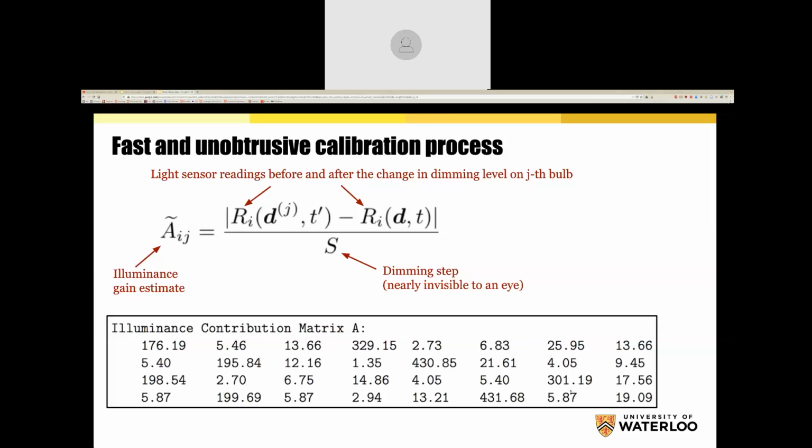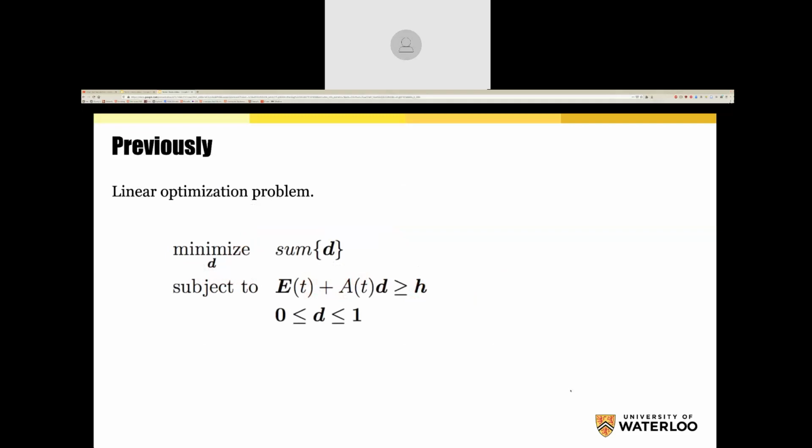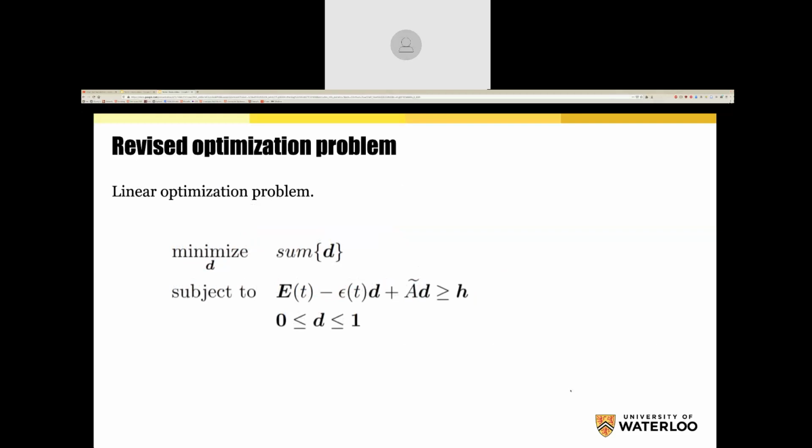That's okay. So this is essentially identical to channel state information, CSI, measurement in Wi-Fi. If you look at 802.11n, this is exactly the CSI. We can think of each bulb as being a separate subchannel. And we have orthogonality due to photons. It's still the electromagnetic spectrum, but we have non-interference because photons don't interfere in the light regime, unlike interference in the radio regime. So it's pretty neat. There's a very clear mapping to Wi-Fi, actually. Anyway, I won't go down there.